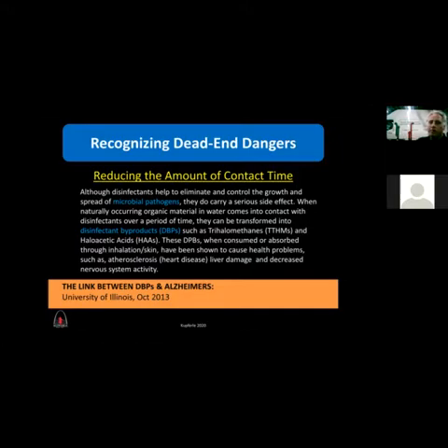The EPA has known about DBPs for some time, since the late 70s, and thus we've had our Stage 1 and Stage 2 disinfection byproduct rules implemented. We're currently under the Stage 2 rule, and now you need to take your quarterly samples and stay below certain levels of DBPs that the EPA prescribes. If not, you have to take action, and an easy action for controlling DBPs is flushing dead-end lines, to get the old water out, bring the new water in, before your disinfection byproducts start to form.